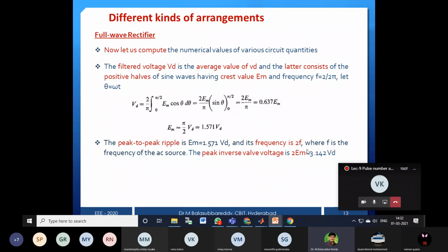But in the normal full wave rectifier or fully controlled rectifier, which is a bridge type, you will get only a peak inverse voltage of Vm. In that case, for whatever load you want to connect, the midpoint converter requires a high rating of the device. That is the major drawback also. Obviously, cost.